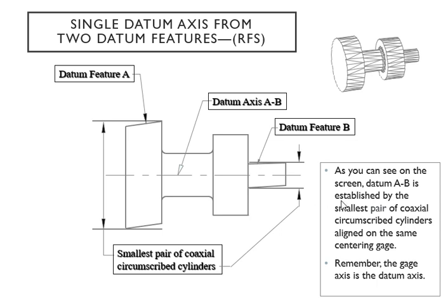So anyway, you can see right here your datum AB, which are equally important to each other, which is your primary datum. In this case, your axis is showing right there very clearly. Your B and then your A are going to be right there for their corresponding features. And they are, of course, coaxial circumscribed cylinders because you're dealing with the axis. Of course, you have the same centering because they're sharing the same axis.